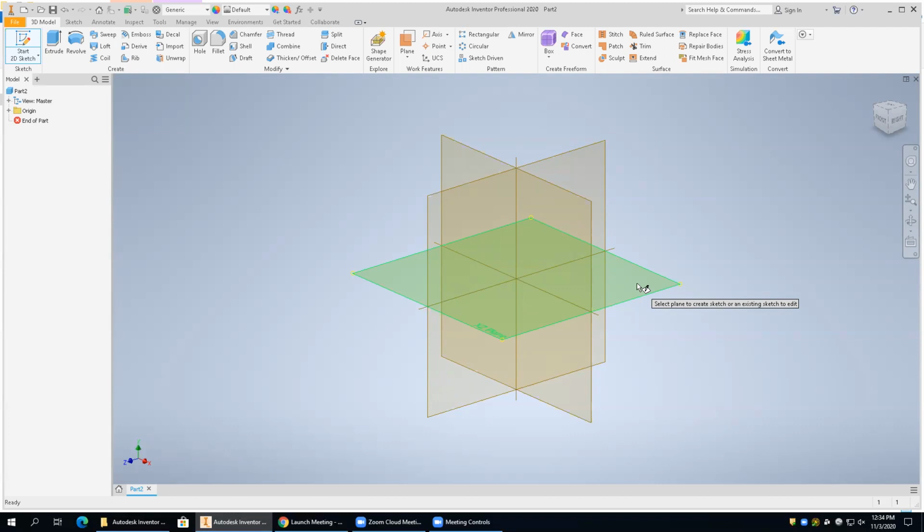Okay. So what I mean by that, I know my guys in the other room can't see this, but if I have something that's just a rectangle and I notch corners off of it, I might just try to draw it something like that, but I'm not going to worry about the exact values because I'm going to drive it with dimensions later. If I have rounded corners, there's a couple ways I could do that. I could fillet it in that sketch, or I could fillet it after the fact. Okay. So I can keep it really, really simple and do editing after the fact at any point. That's the one thing about it. But the idea is to keep it simple.